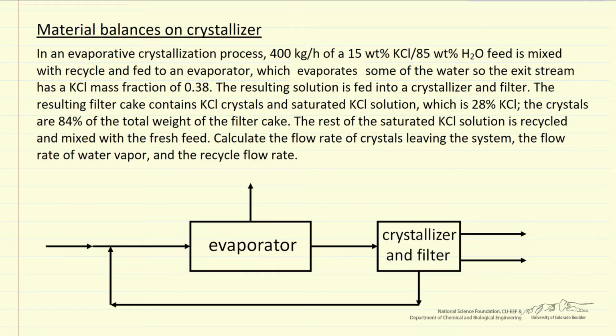In this screencast, I want to demonstrate the idea of recycle by carrying out a calculation where we evaporate water from a potassium chloride solution and then filter out solid potassium chloride and then recycle the remaining solution, remix it with the feed. So what we want to do is carry out mass balances for this system.